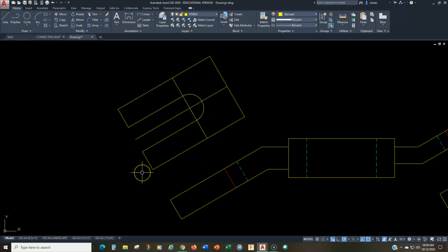So far, so good. Now, we're not quite done yet. There is a curve on the end here, right? There is a curve on the end, which I do not count as a fillet or a round. Why? Because it's a rounded end. It's not taken care of with the fillet and round dimension R5 in your textbook. This is a radius 12. So this is different, so you will need to put this on here.